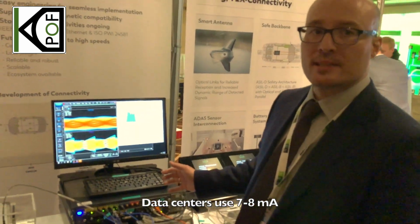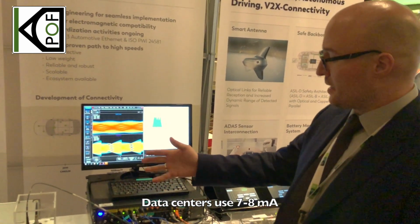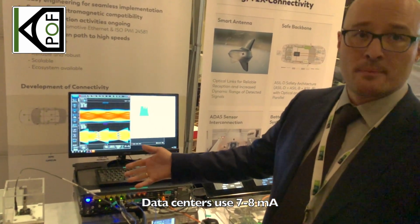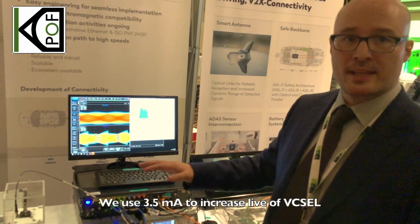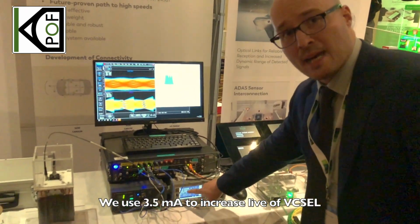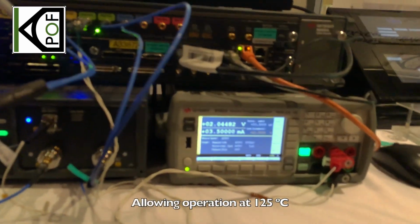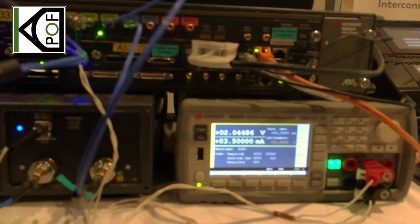Typically, in order to get these very high speeds in data centers, as they are using the same pixel device at data centers, they need to use between 7 and 8 milliamps. But here, in this demo, we are using only 3.5 milliamps in order to increase the lifetime of the device, and it needs to operate at 125 degrees.